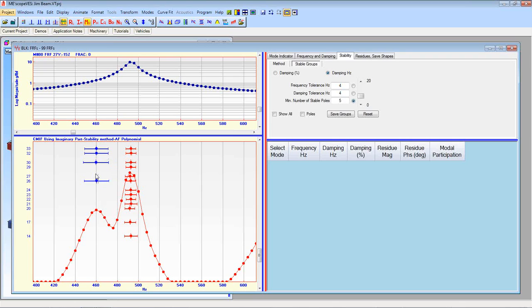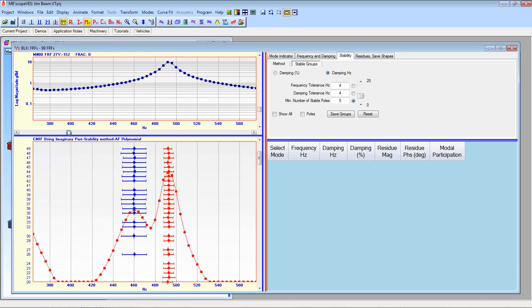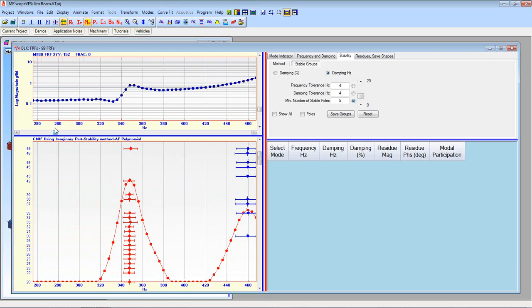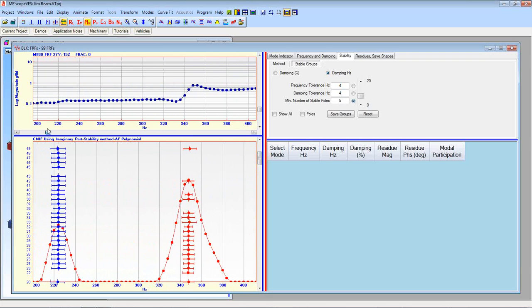The damping, remember that damping in hertz, is the half power point damping, or the width of the resonance peak. And you can see here that here's 2 modes that are fairly close together in frequency. You might say they're closely coupled, but their damping is quite different. Now, we won't go into the discussion of why that's the case, but that's true in the physical world, that we can have 2 different modes that are very close in frequency, and their damping is quite different.